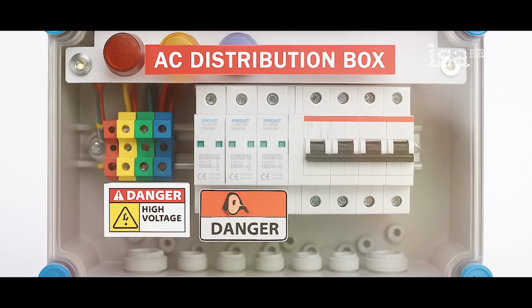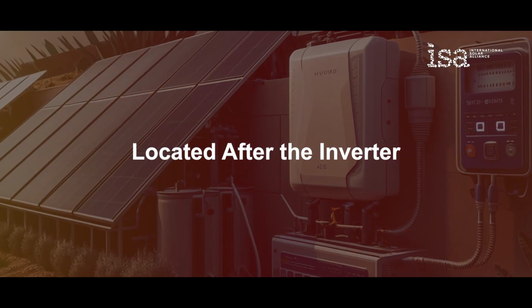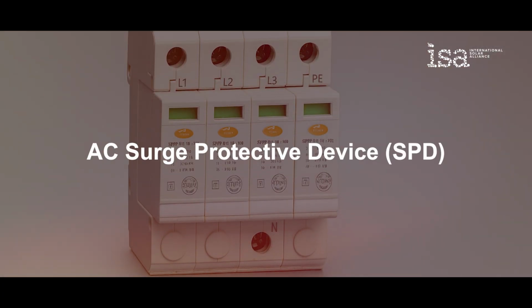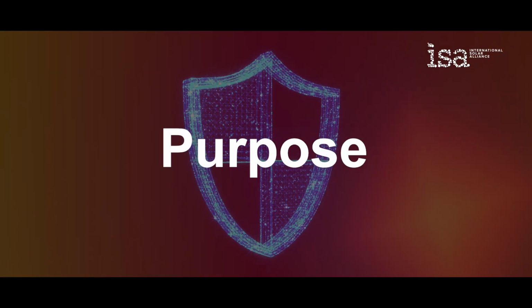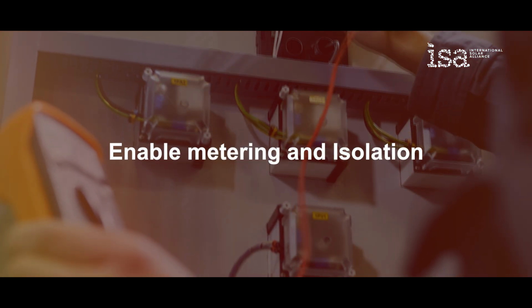AC distribution box, AC-DB, located after the inverter. The AC distribution box manages AC output, includes AC MCB/MCCB, AC SPD, isolator, energy meter, changeover switch in some systems. Purpose: protect AC circuits, ensure safe grid connectivity, enable metering and isolation.